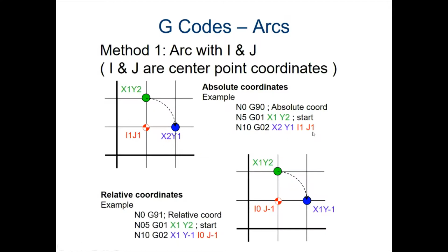The other thing we can do is relative coordinates. And again, with relative coordinates, we are not referring to where we are on the XY coordinate grid. We are just referring to how far I am going from where I currently am. So again, here I am going to get to this initial starting point somehow or another. In this case, I'm in this relative command, so I relatively somehow have gotten to this position. This is where I'm at.